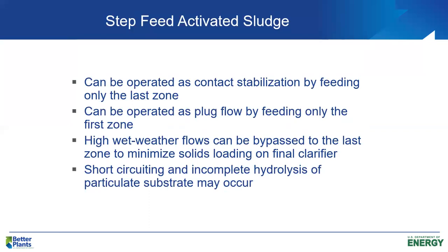So again, some of the comments I just made are stated here. The opportunity to operate in plug flow or contact stabilization mode, and being able to handle wet weather events without washing our biomass out. One problem, if we do put all of the influent in the last compartment, we risk the problem of short circuiting and poor hydrolysis of particulate organic matter that's coming in the raw wastewater.